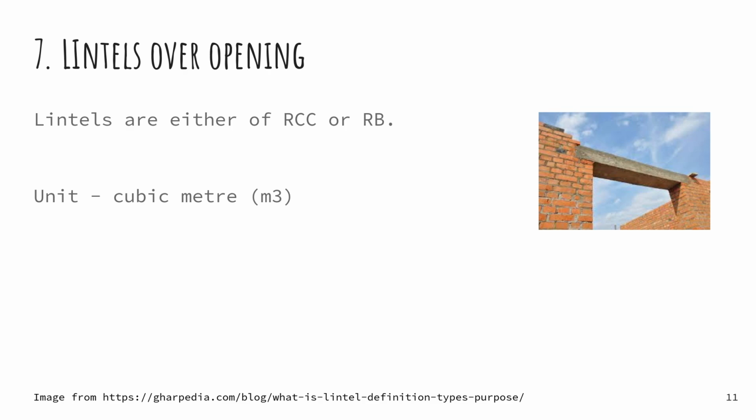the load of all the bricks and the building parts that are above the door will come directly onto the frame of our door. So in order to reduce the load that comes to the door frame, we actually provide a lintel so that the load that is coming towards the door actually gets spread out to the two portions of the wall surrounding the door.